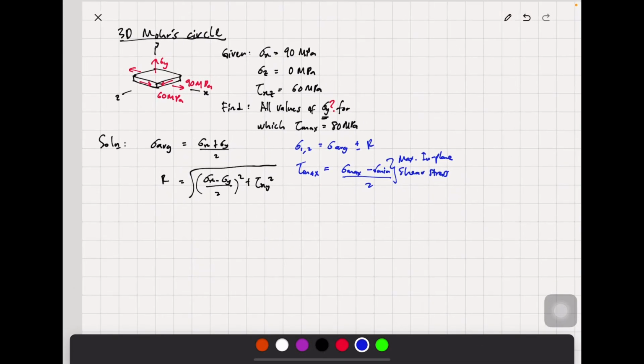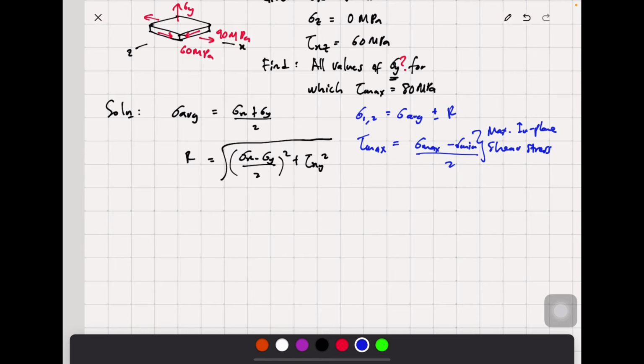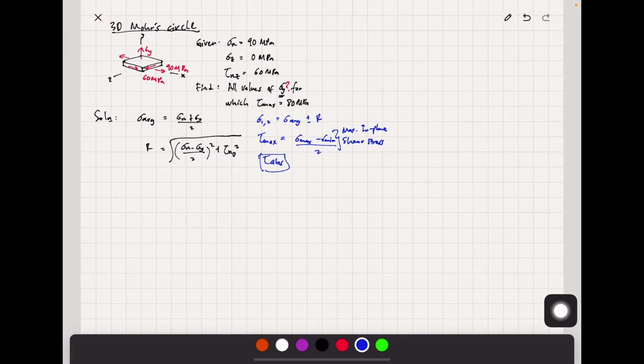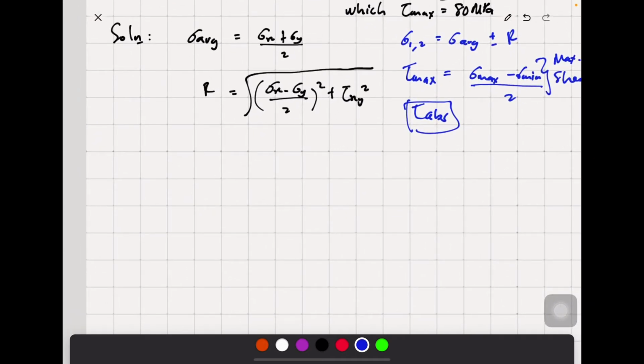Looking at the absolute maximum, when you are given sigma x, sigma y, and sigma z equal to 0, another, probably bigger, circle can be developed out of your Cartesian chart, and that bigger one, the largest radius, is what they call the absolute maximum, which is the largest radius on your Mohr circle. We haven't done this yet, so it is good to go ahead and calculate using the values.